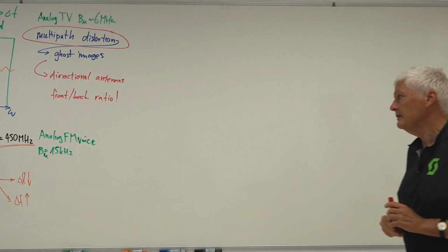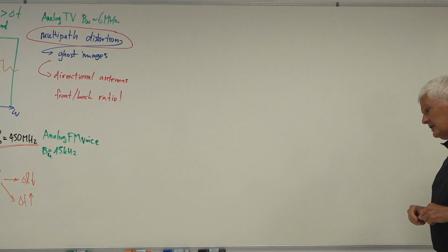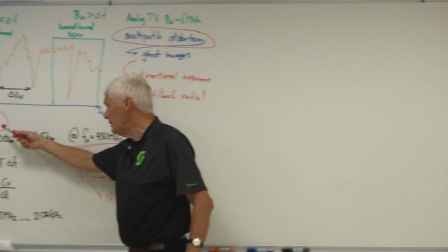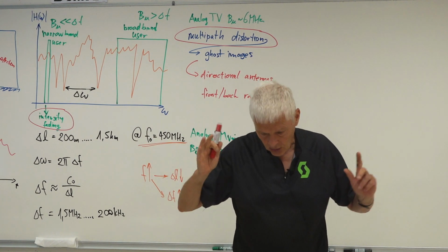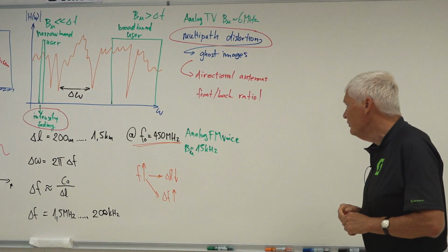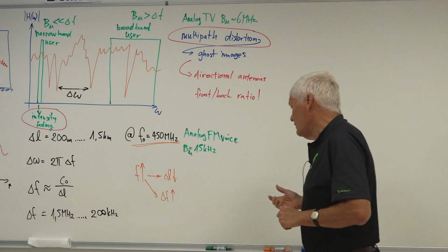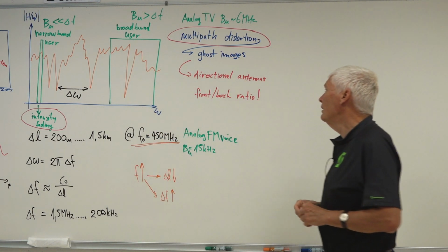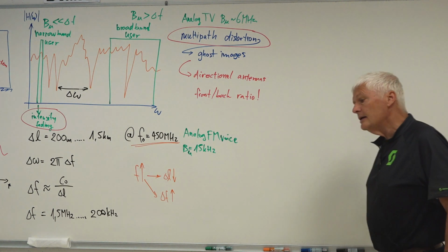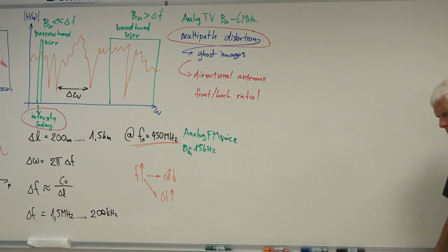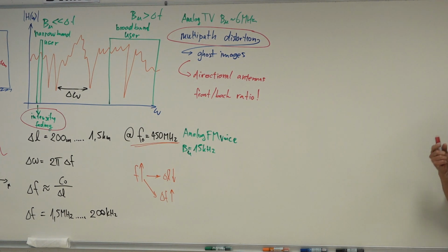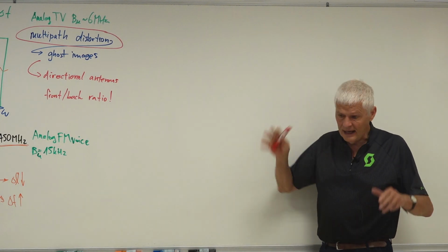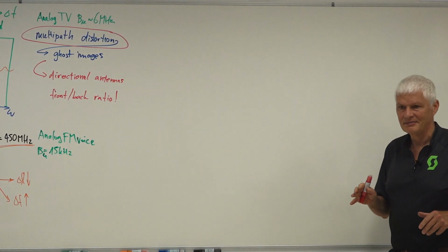So that's different. And also the countermeasures were different. Maybe for intensity fading, just an automatic gain control in the radio receiver, audio radio receiver, was enough for this purpose. Even in a radio receiver installed in a car, in a vehicle. While for multipath distortion, quite complicated solutions had to be used. Receivers had to use highly directional antennas. And that was quite a big market, selling the antennas and installing those antennas for analog TV sets.